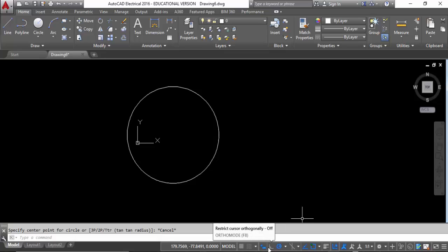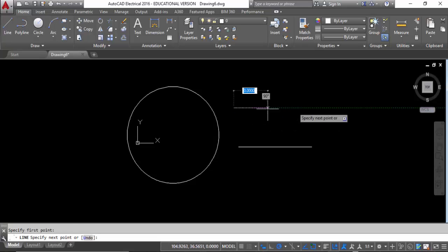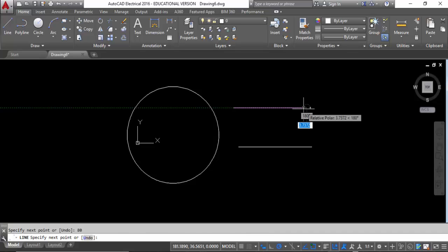Right, if I go to the next point here, we've got a dynamic input. If I place dynamic input off and I select a line, you'll notice that I can type in maybe 80 mm or whatnot, but I have to read my command line to actually see that that input is accepted. Then I press enter and it's there. However, if I place in my dynamic input and select the line, you'll see that I can type it in here, 80, and it will then allow me to see it directly on the screen. Okay, so that's dynamic input.